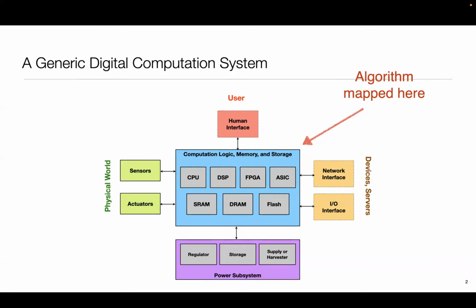What do we use? Anyone? How do we convert analog information to digital information? ADC, right? So an ADC does two things. It discretizes in time, like it samples the signal. Some of you may have heard of Nyquist sampling, for example. Essentially, the idea is I can take a continuous time signal, sample it at a certain specified rate, and then there are theoretical frameworks like Nyquist sampling, which allow you to reconstruct the signal.